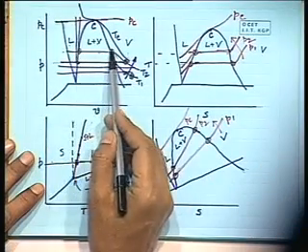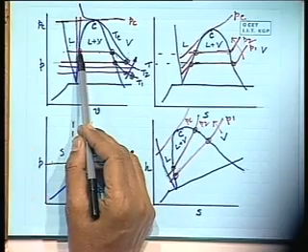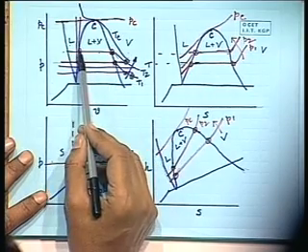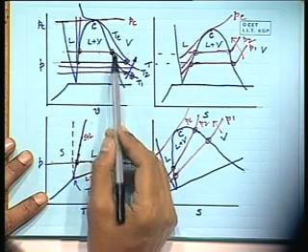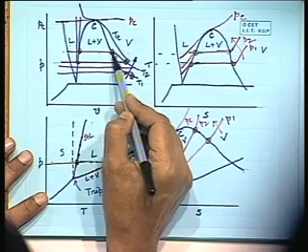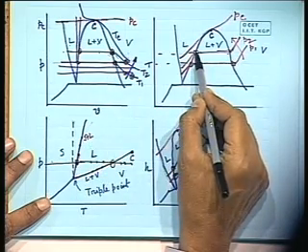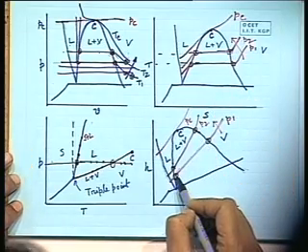These are the saturated states and the properties are well fixed. That means this has pressure and temperature the same, but other properties, the specific volume of saturated liquid is fixed, the specific volume of saturated vapor is fixed. This vapor is known as dry saturated vapor, that means completely dry vapor. Here the entropy is fixed, and the enthalpy is fixed.